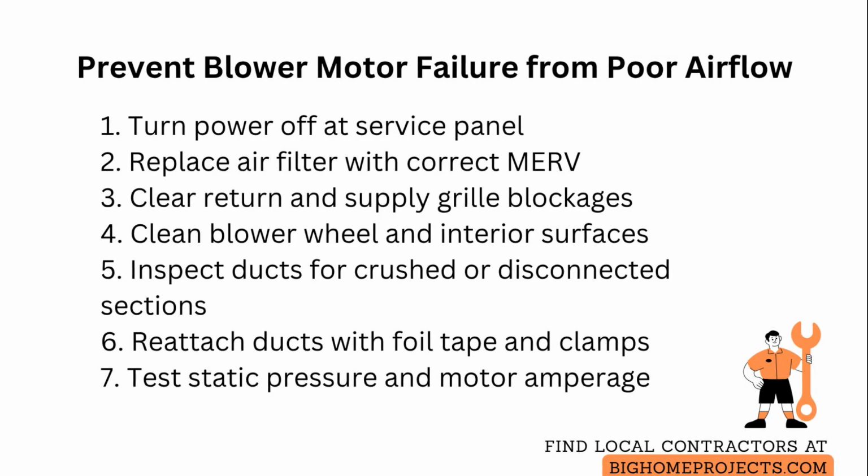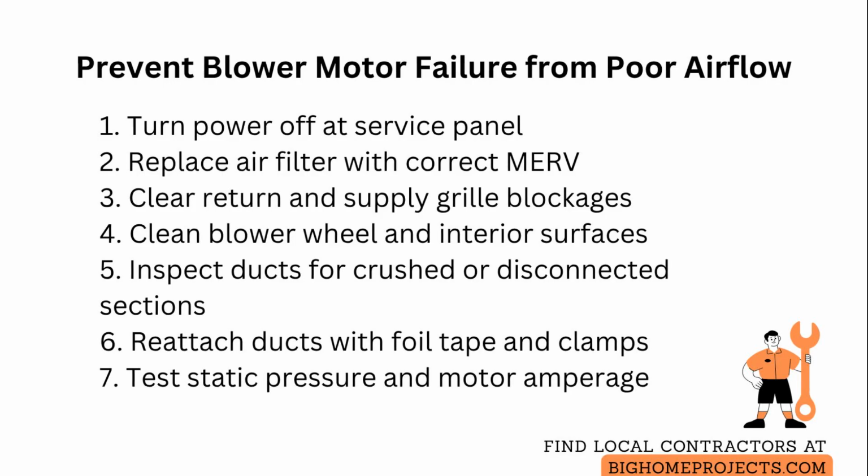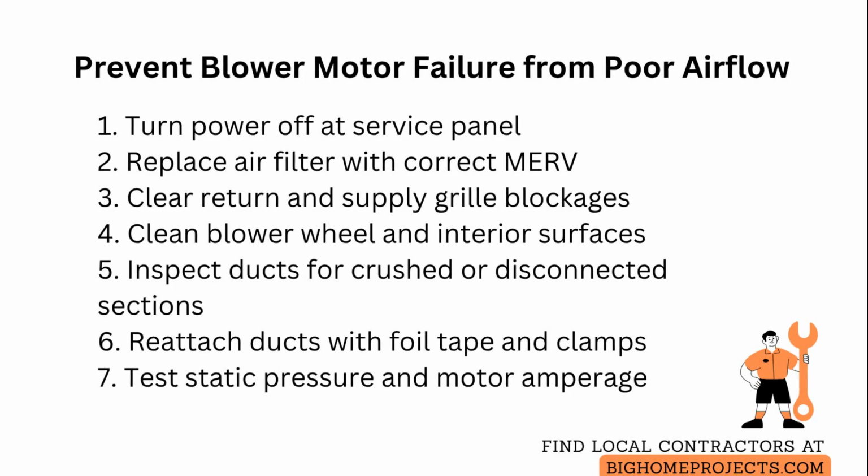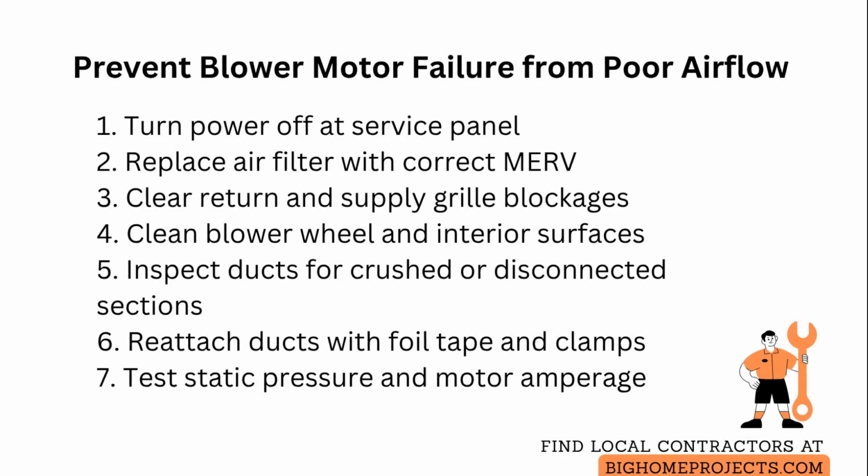Remove the blower access panel and look for dust accumulation on the blower wheel, motor, and internal surfaces. Gently brush and vacuum debris and use a vacuum extension to reach crevices without bending fins. For ducts, perform a visual inspection through access points and registers.